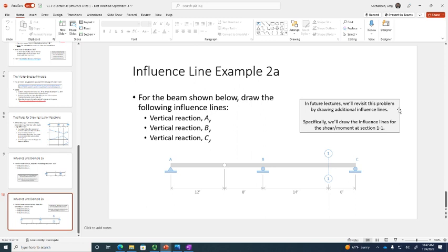But let me say this. In the land of bridges, it is conventional to cut every 10th point. So if a span is 20 foot long, it's typical that you cut at 2, 4, 6, 8, 10, 12, and all the way across the span. So 10th point, because you can only evaluate shear and moments at discrete locations, so you need enough of them to be accurate, but the more that you do, you start getting to a point where accuracy doesn't matter. So 10 points is conventionally considered what you need to do. Did this make sense? It's weird, isn't it?